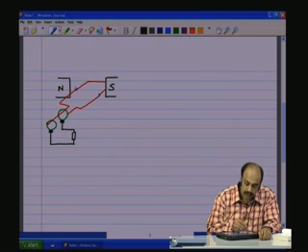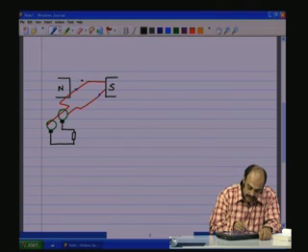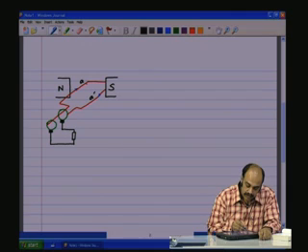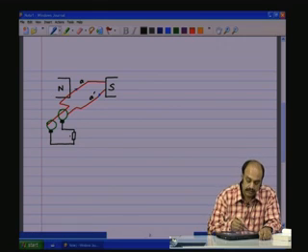Now, here as the coil rotates, let us say this is the coil conductor A and this is coil conductor A dash. The current through A is positive, let us say this direction is positive, and as this comes into an orthogonal plane, that is perpendicular to the north-south axis, then the current through A and A dash will become 0, and then on further rotation the current through A starts going negative and the current flows in the opposite direction in the external load, and as it keeps going in this manner, it takes a sinusoidal wave shape pattern in the external circuit.